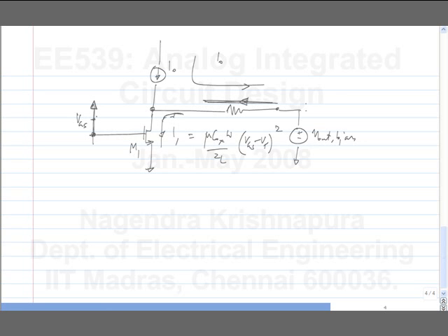You still have to make sure that you can do that, but it looks like by raising VGS I can increase the current, whereas the other side I can't do anything like that. Because it is limited on one side, for symmetrical signals, the peak value is limited. So to get a desired peak value, you need to have a sufficient bias current in the output stage.